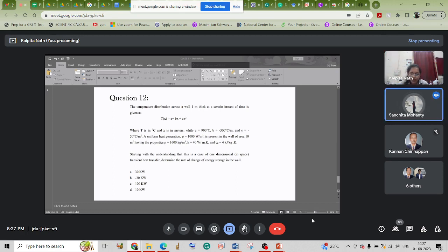See, you will just use Fourier's law for solving the heat flux, right? Then you just use the heat flux and balance it out with energy in, out, and everything. The main equation is: if there is a body, energy is entering, energy is leaving, energy is generated, and some energy is stored. How will you balance it? And the flux, you just replace it with Fourier's law. Understood? Yes, ma'am. I'm trying. Yeah, do that.